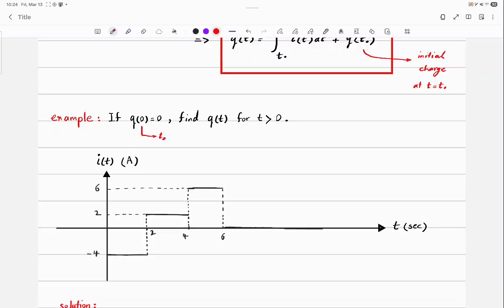Okay. For element B, someone else, please. The current remains constant, so we just use the same current. Yes. So you agree that this current is negative 2 amps, right? Why is the current the same? Because the line doesn't branch out, it's the same. Perfect. It doesn't have anywhere else to go. So all of it must come down. So how can you find the absorbed power of element B?